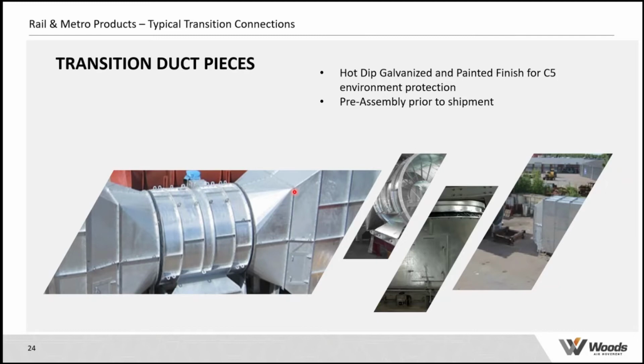What we did there was design it in that way to try to reduce the pressure drop as much as possible. And again, these systems generally need to be symmetrical because we want to be able to operate in both supply and extract mode. So we want to have a similar system resistance in either direction.